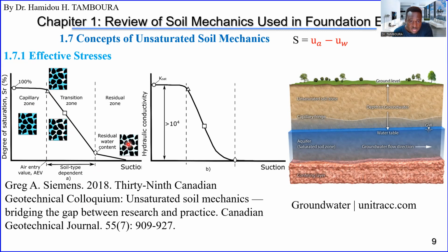Like the water is thin on the soil particles, but the majority of water is gone. That zone is called the residual zone. And we can say that the hydraulic conductivity is decreasing when the suction is increasing. This is just for your information.